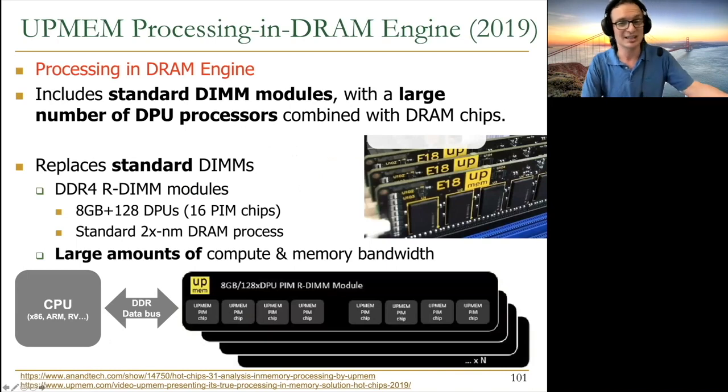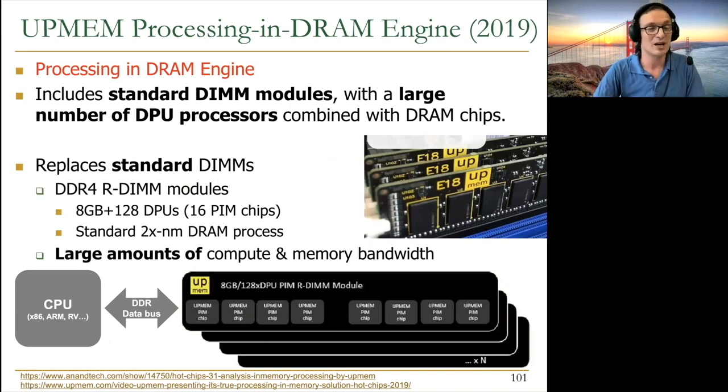And as I mentioned in earlier lectures, processing in memory systems are real right now. They're real systems. This is one example of a real system, the UPMEM system. It's a company in Grenoble, France, very close to Switzerland, and we work with them quite a bit, actually. What they've done is essentially add processors in a DRAM chip. They call them DPUs, DRAM processing units.